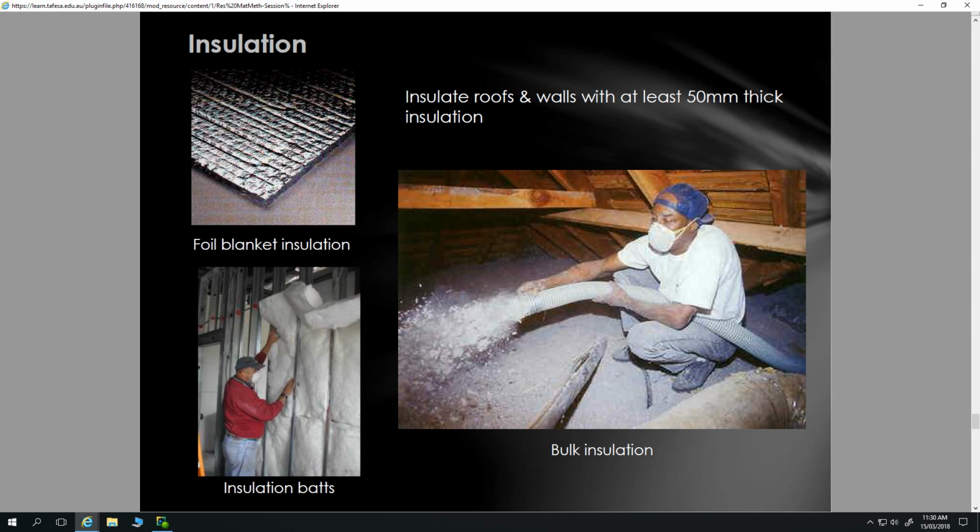But that sort of thing, I just put it in a shed. So build a shed, use that in the shed, fantastic. There are no requirements for insulation, and you're not going to put roof bats or whatever into a shed, but to have an insulated sarking like that just provides a lot more comfort in the shed, and although it's fairly low R value, it stops a lot of that radiant heat that comes from the roof. So you've got your reflective foil on the top, and you're not getting the heat from your sheeting inside the shed. So great application for that.